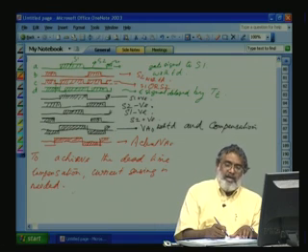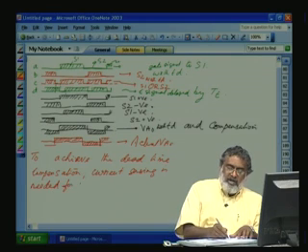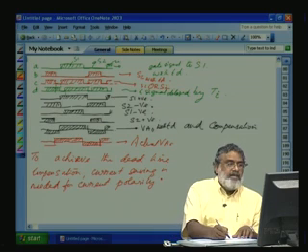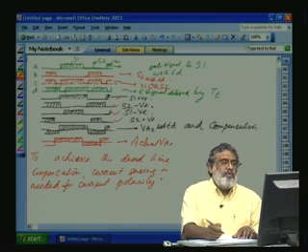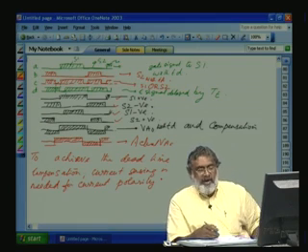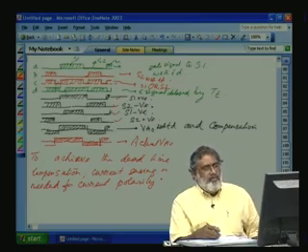So, depending on the current polarity, we can give the gate signals S1, S2, S1 negative, S2 positive, based on the original signal with the dead time. So, the whole dead time is divided by TD only. This way dead time compensation can be achieved. There are various techniques available. This one technique makes it possible to compensate the current and voltage distortion in the output voltage during PWM operation with dead time.